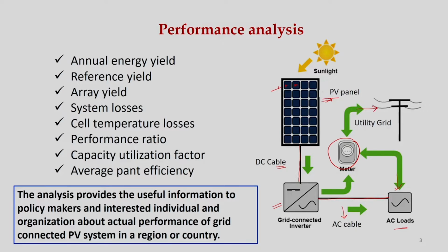When we design, we need to know what the output will be, what the losses are in this cable, what the efficiency of this inverter is, and what the losses are in this cable. Other components like MPPTs are also attached here, so what will be the efficiency of the MPPT. All those components we need to consider when we talk about performance analysis of a grid connected PV system.